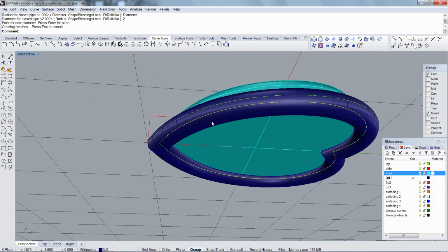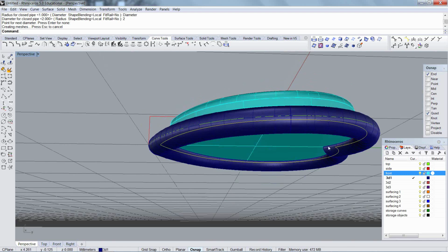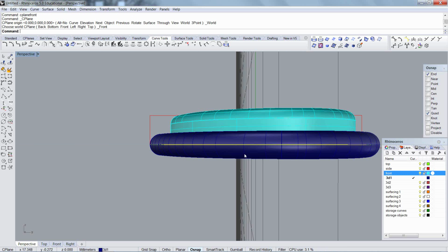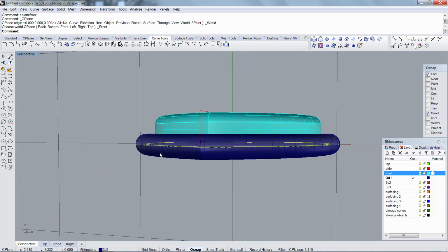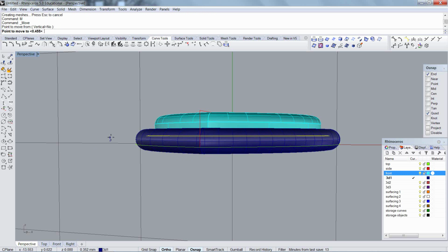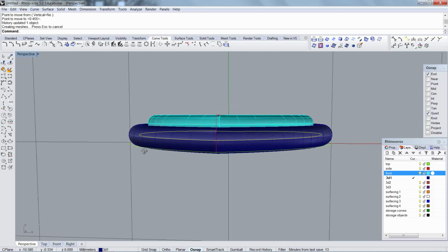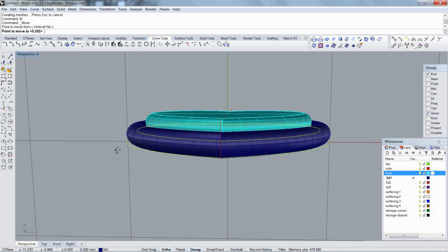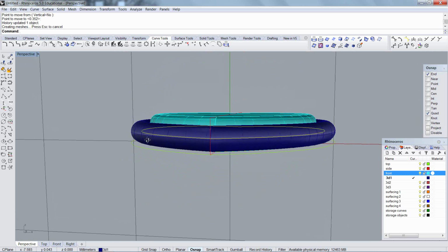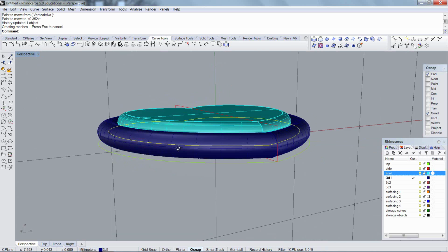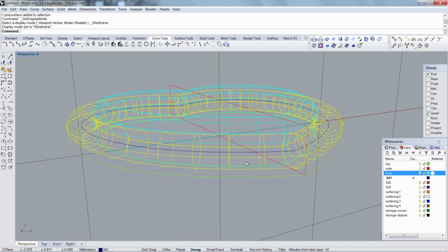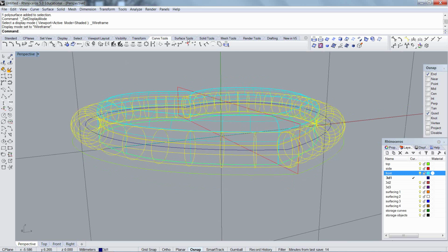Of course, since the pipe was on the ground, it's sitting in the middle of the bottom edge of my piece, which I do not want. Go to my vertical C-plane, move my parent curve up, and the pipe will follow. I'm going to move it up until my piece is kind of hanging out the bottom a little bit. That's good. Okay. Going to do a cutting plane.